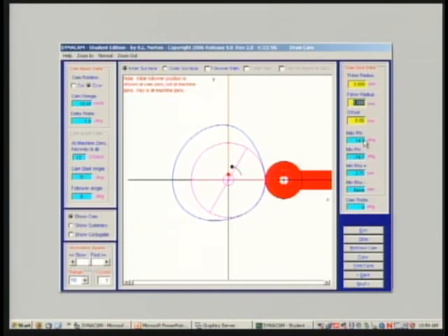I have a maximum pressure angle, which is called phi, of 14.5 degrees and a minimum of minus about 17 degrees. And the rule of thumb for translating follower, as you may have read in your book, is about plus or minus 30 degrees. The minimum radius of curvature has been calculated to be, in a positive sense, 2.7 millimeters.